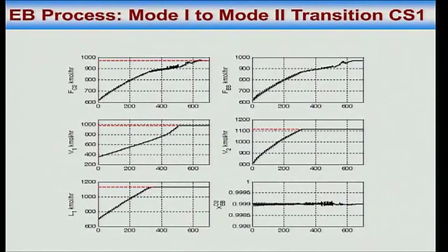Then I think last but not least, you keep changing the set point. You want to increase the throughput, so what we are doing is we are increasing the V1 set point by 10%, okay, and taking it to max. And what you find is that the FC2 keeps increasing. The rate of increase changes because constraints are becoming active.